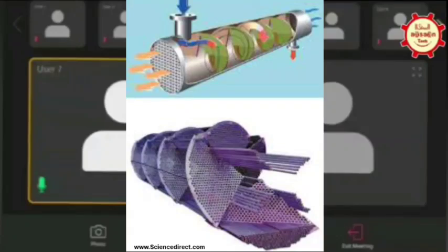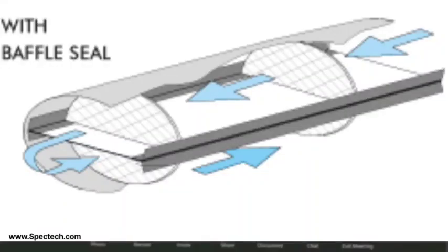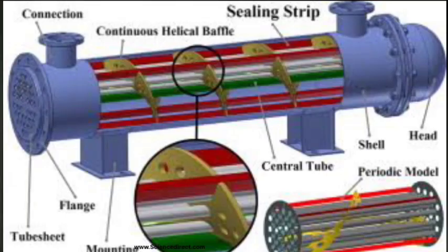I want to add, Sheikh. I think they are talking regarding the sealing strips, which are used as a longitudinal strip to reduce the clearance so that the heat transfer is effective. It's like a sealing arrangement, as there is a clearance between the tubes and baffle.